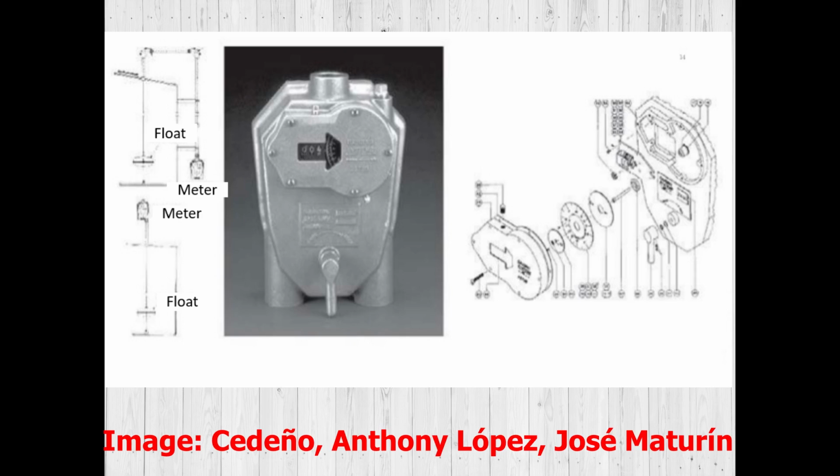The last direct measurement instruments that I will talk about are the servo-level gauges. These have a displacement disc suspended by a stainless steel cable, which is coupled to a precision machine with a grooved drum, which stores or dispenses the cable. This drum is driven by a controlled servo motor and mounted on precision bearings. When the level varies, the displacer rises or falls automatically, maintaining contact with the surface of the liquid.